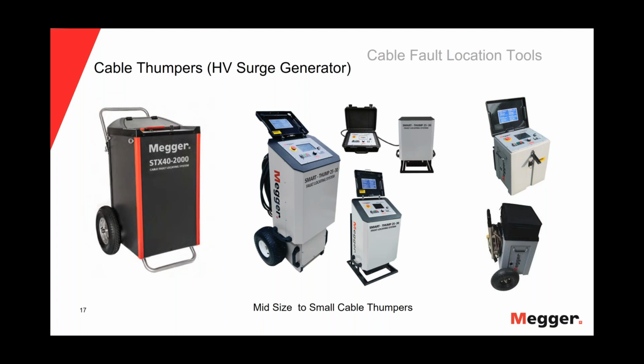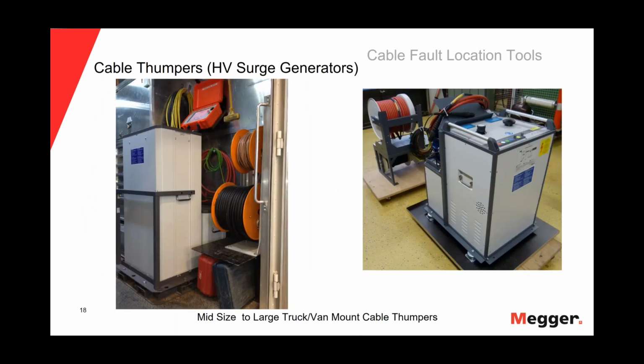But one of the key things about thumpers today is when we start talking about fault locating sequences, some of these thumpers have built into them a fault locate sequence to help the operator move through and find the fault quickly and efficiently. And the earlier slide showed portable thumpers. There's versions of these that can also be mounted in a truck or trailer.